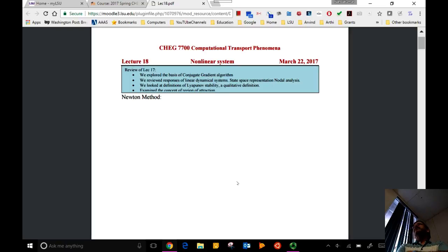So you can start with k-epsilon to explore. That's built in there. And then the Reynolds stress model should be there in COMSOL. But COMSOL is behind in terms of the menu of modeling options for turbulent flow, also for multi-phase flow.